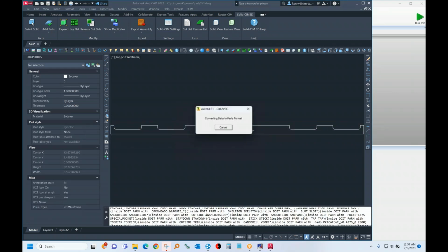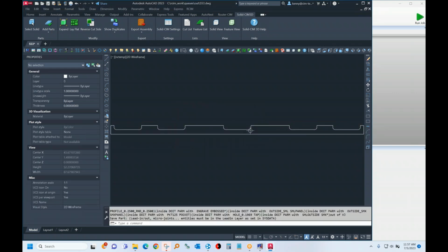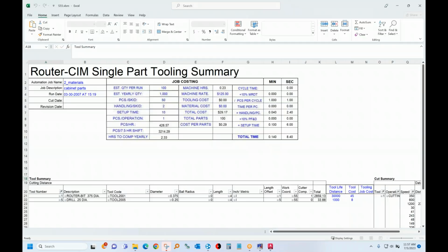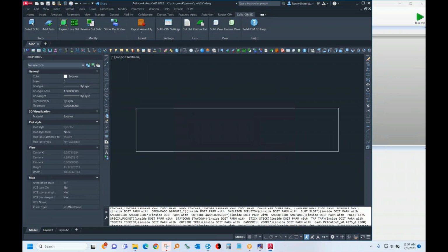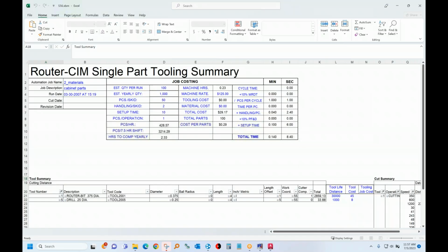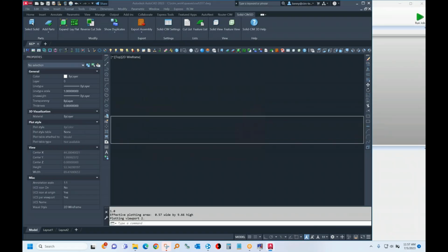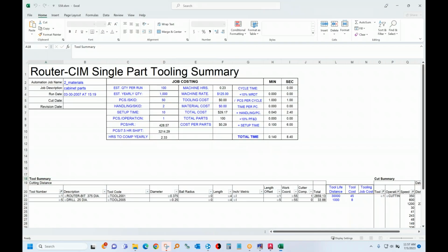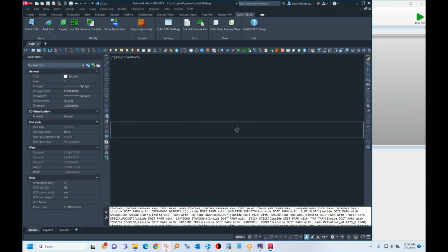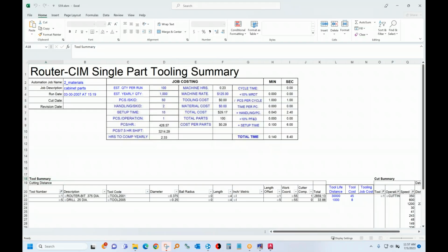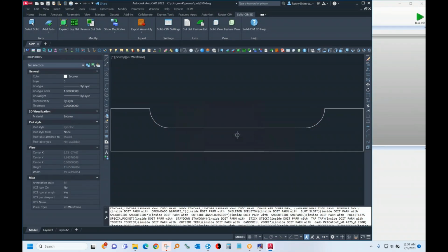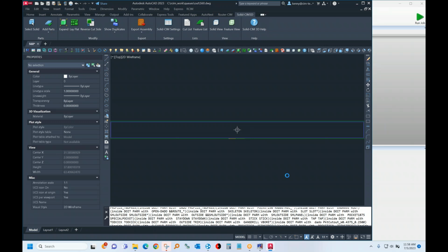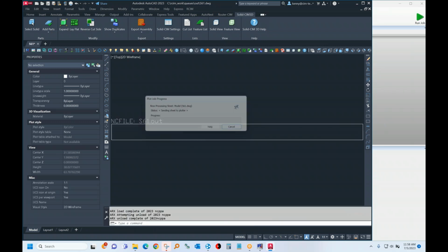We can also do common line cutting, two-sided nesting. I can nest by material size, or price, or yield. So I could set this up so I have 4x8s, 5x10s, and 5x12s, and the software will determine what was the best yield. Maybe 2 sheets of 5x10 and 1 4x8. The best price might be 2 sheets of 5x12. So you could put in the price for each size, and the software will figure out what is the best yield or the best price for your nesting results.